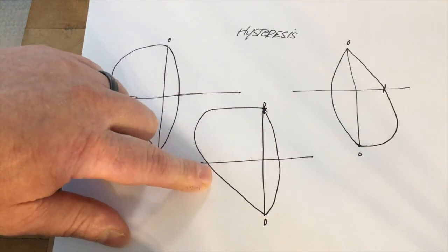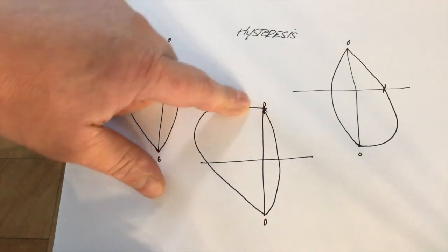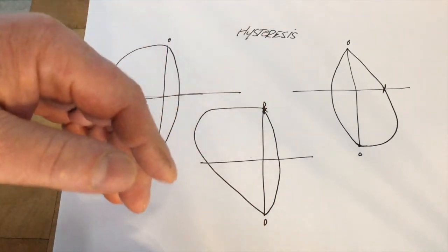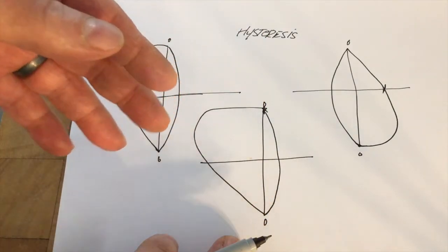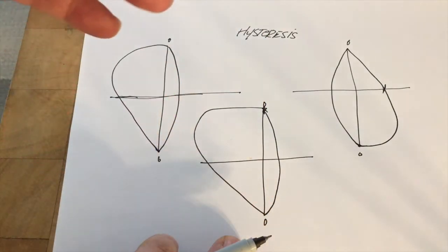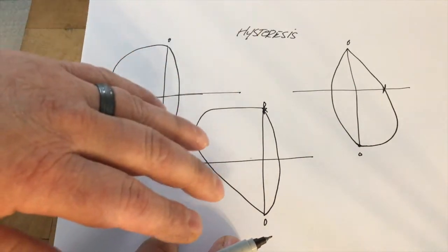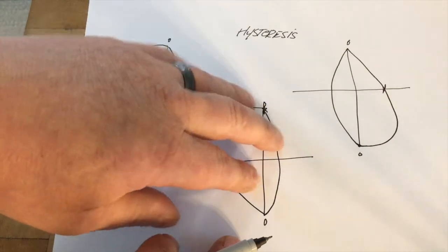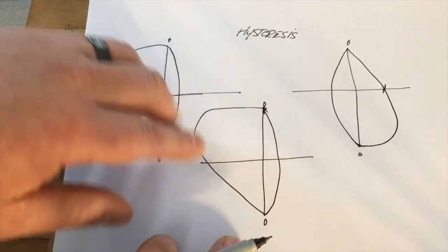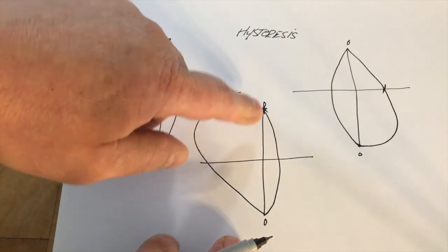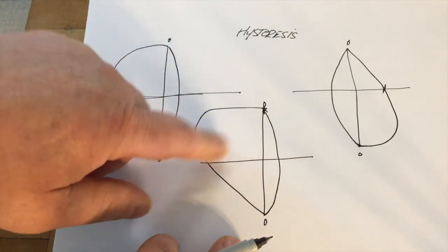I always like the right front if you want to tie it down some, but it should be able to go up and down over bumps. It all has to do with weight transfer and roll centers and soft right fronts and everything, and weight transfer to keep the car on that right front without having to do it with a shock, because doing it with a shock will take traction out of the tire.